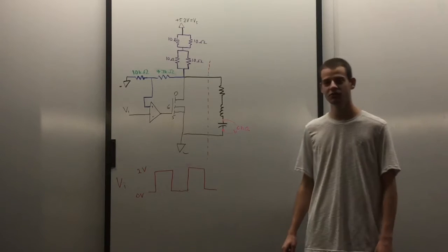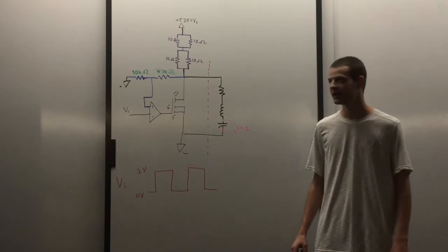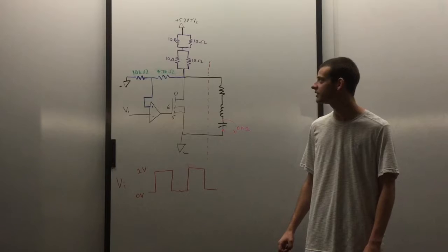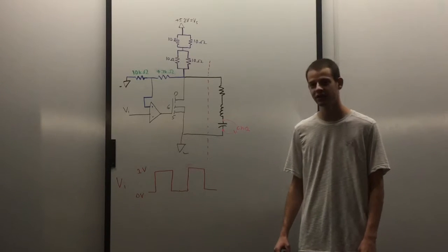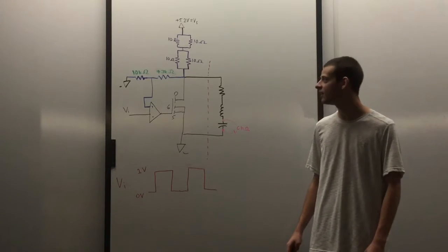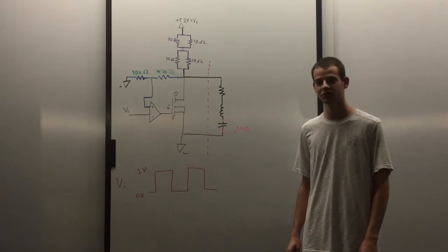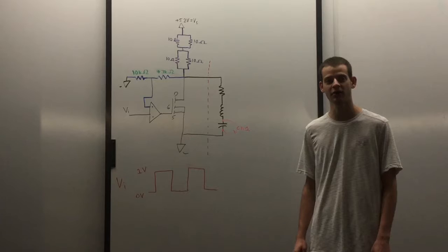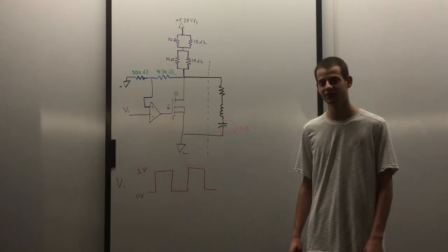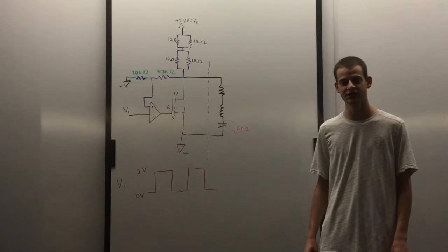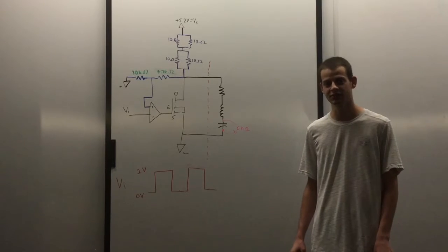And then our second issue was that we burned out 2 10 ohm 2 watt power resistors, which came out of the drain of the MOSFET transistor. And then we replaced it with a connection of resistors which equaled the same resistance, except the heat was transferred over 4 resistors instead of 1, thus making each resistor not get as hot.